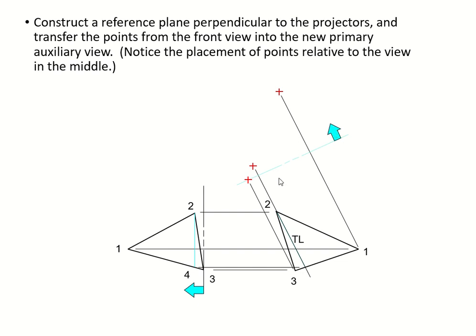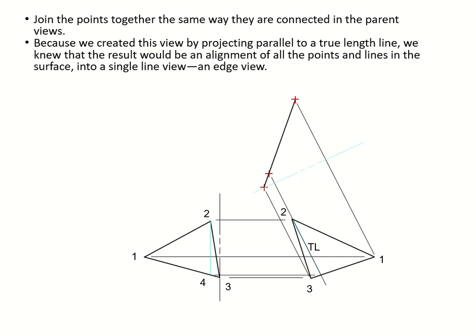Measurement. So do the same thing, all points: 3, 2, and then 1. Draw it, that's your edge line, because we always draw the edge view from the true length projections. So this is our edge line coming from your point 3, 2, and then 1.